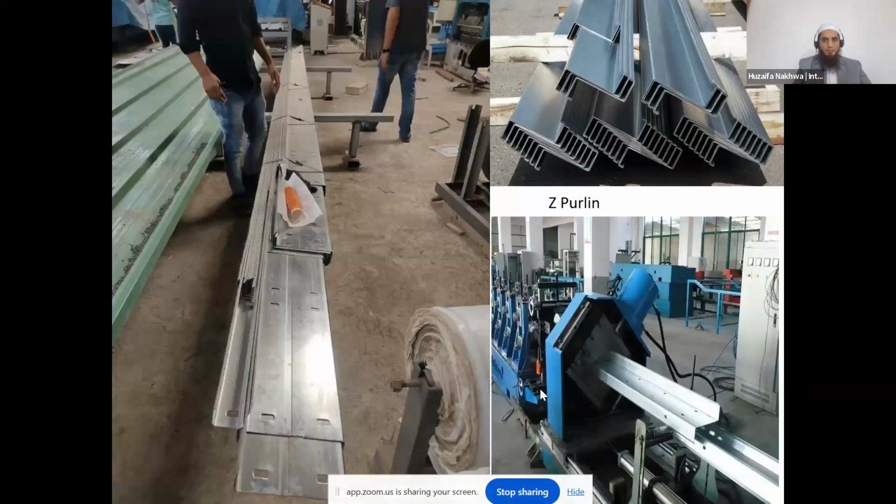This is a purlin machine. Okay, where we bend the purlin. It is cold formed, as the name shows you. A cold roll is placed in a machine, and according to your sizing, according to your hole punching, it gives you slotted holes here, which are slightly adjustable on site. Okay. And this depth may vary around 200 to 250.